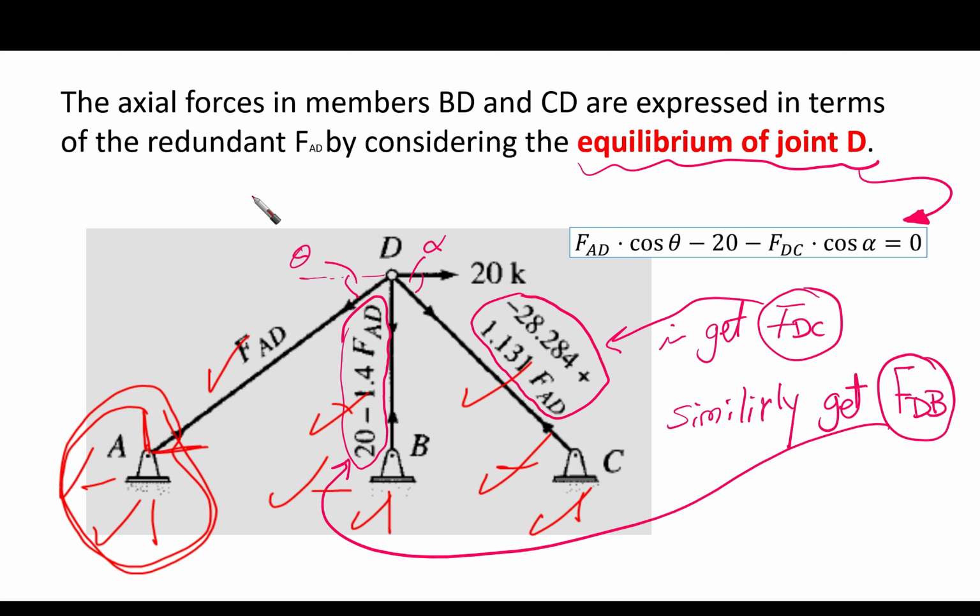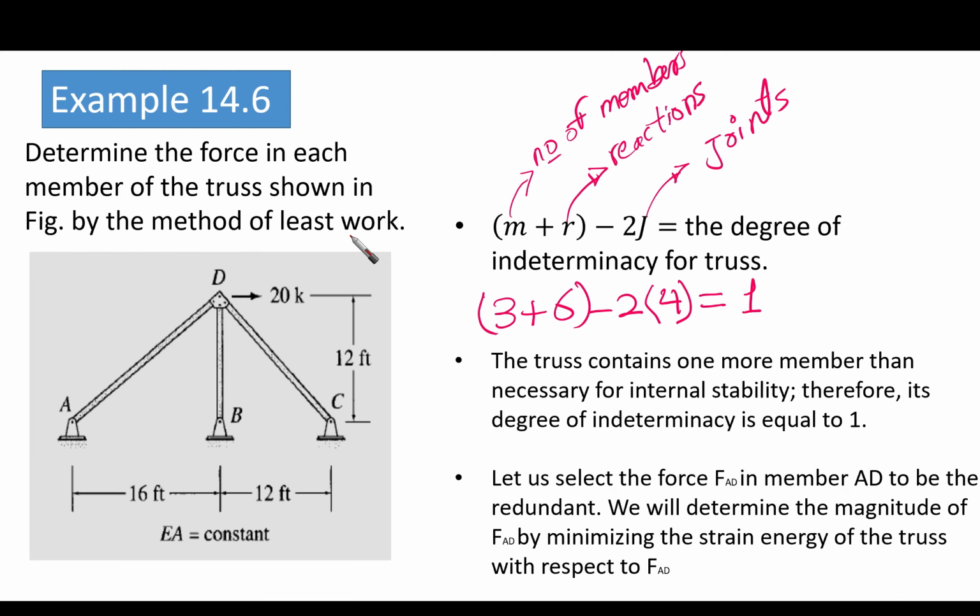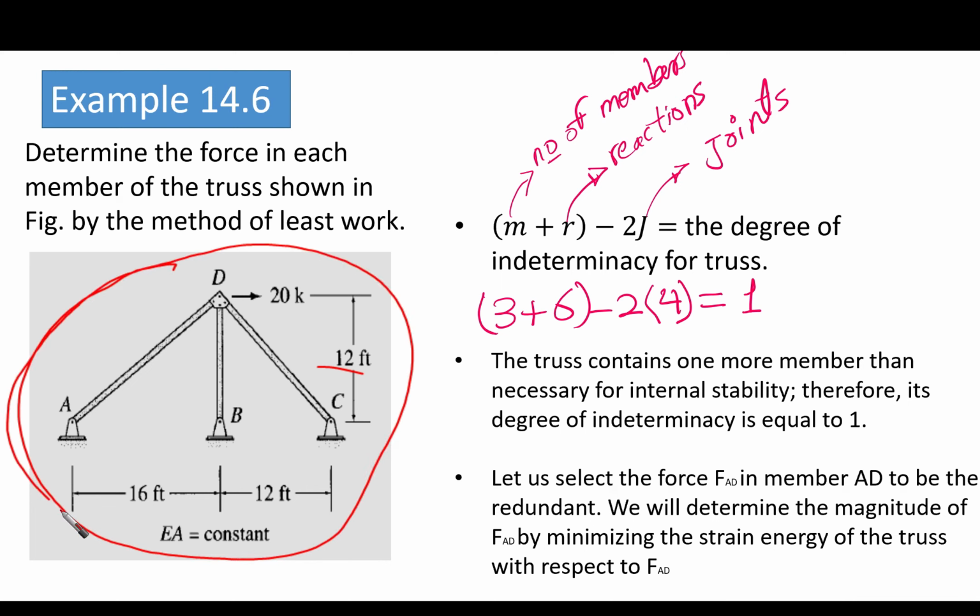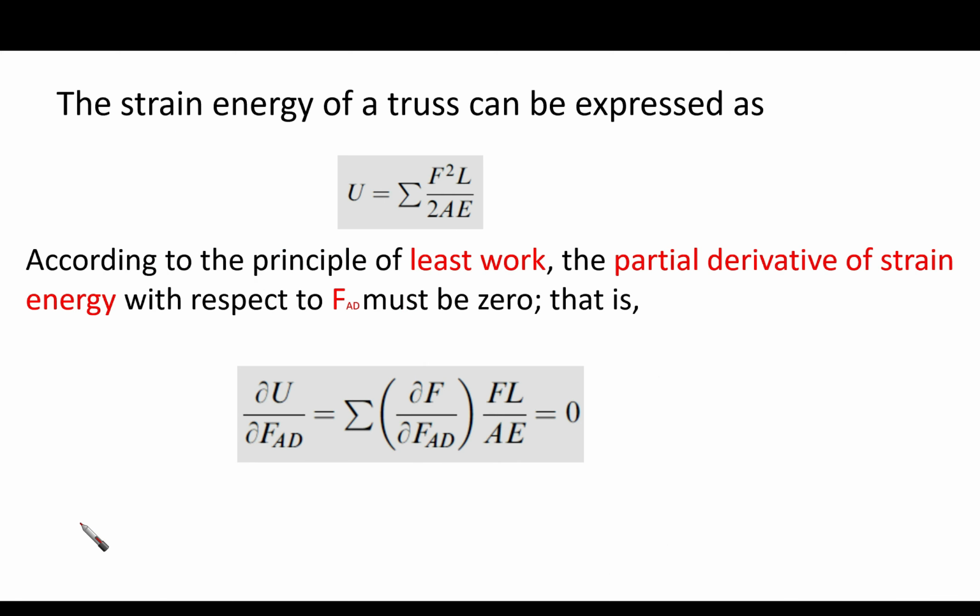Now we have understood the flow of the least work method for our example, based on an application related to axial force members only, which is the truss in our case. Remember the main differences: we are using a summation sign, not integration, and at the same time we are dealing with forces, not moments, and in the denominator we are using area instead of the inertia.